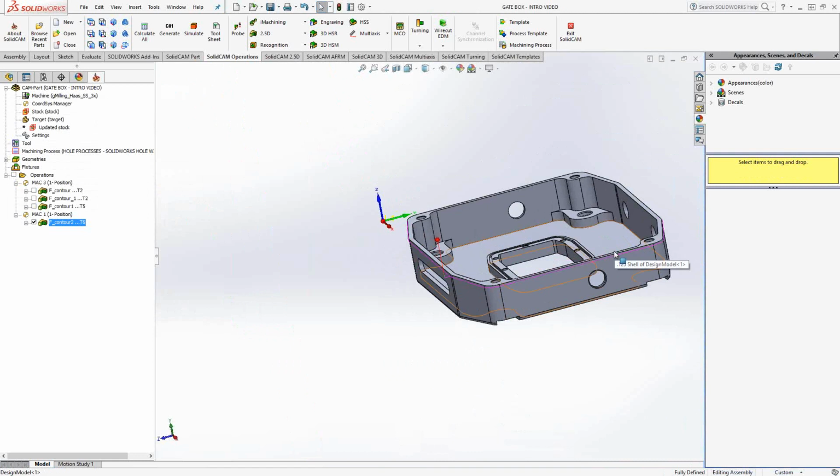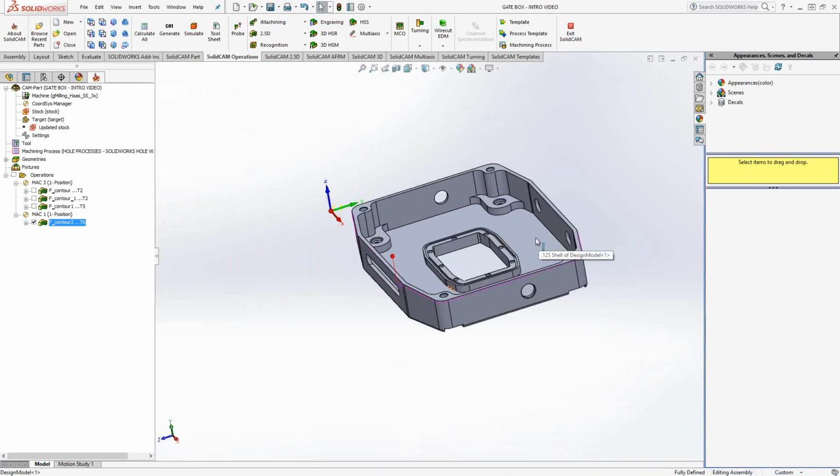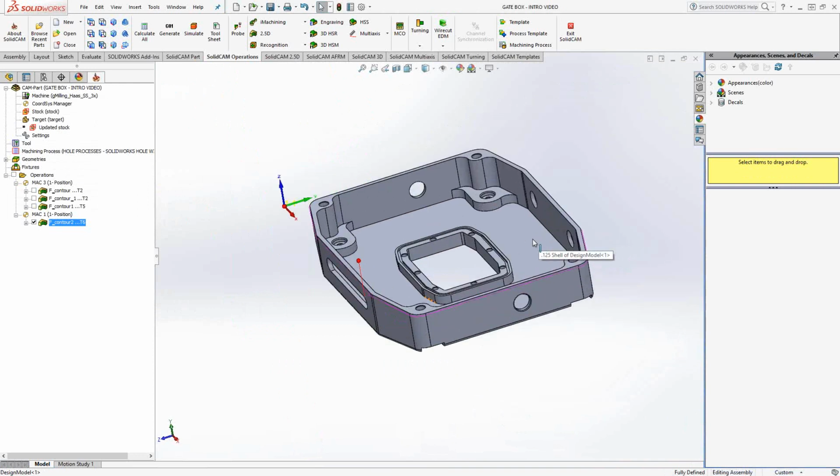Okay. So like I said, the profile toolpath is a routering toolpath. It follows that tool exactly. You have chamfering options, and you can modify any geometry you choose to add offsets, extensions, start points, that sort of thing. You never have to create sketches to get the profile to work. You use the geometry right from the part.